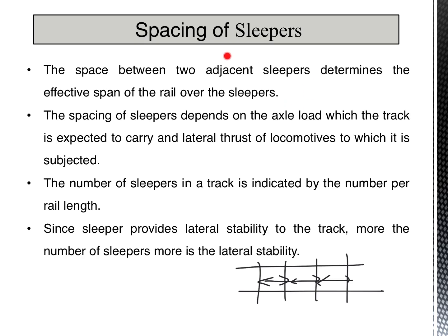That sleeper spacing will determine the effective span of the rail over the sleepers. Also, the spacing of the sleepers in the track depends upon the axle load which the track is expected to carry, and also the lateral thrust of the locomotive to which it is subjected.